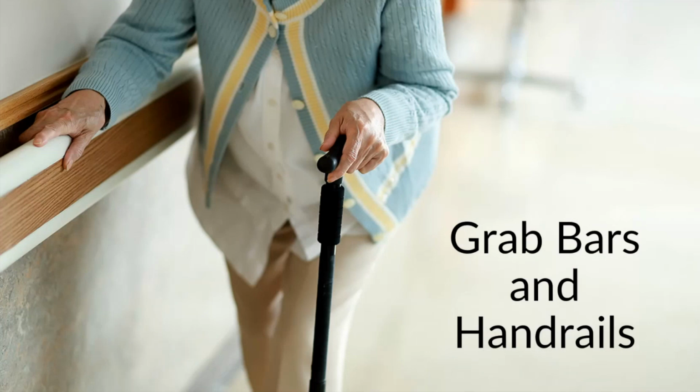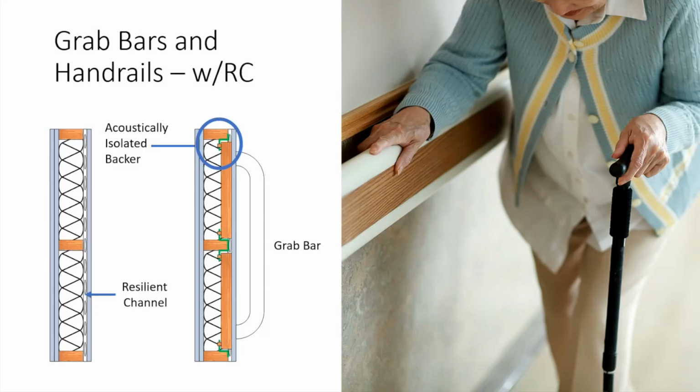Similar sort of thing for grab bars and handrails. Say maybe you're doing a retirement home or assisted living facility or a hospital, and you've got sound isolation between your corridors and your units, but you've got a handrail along there, or you've got ADA compliant bathrooms that have grab bars in them, right? And some of those grab bars happen to be on a demising wall where you need acoustical isolation. So same sort of thing, right? You use an acoustically isolated backer.